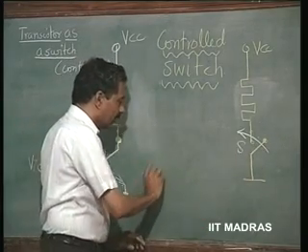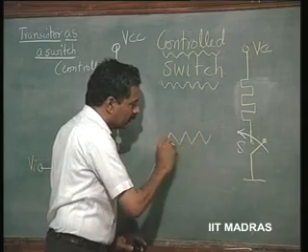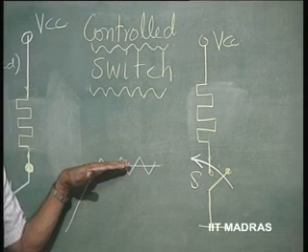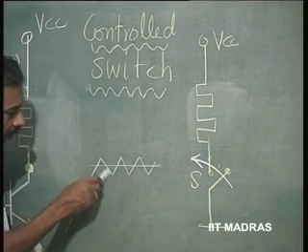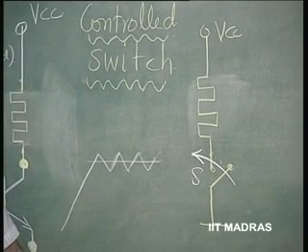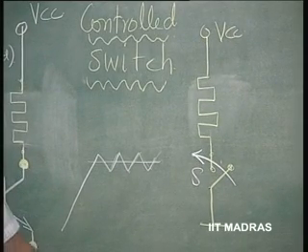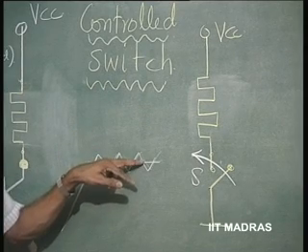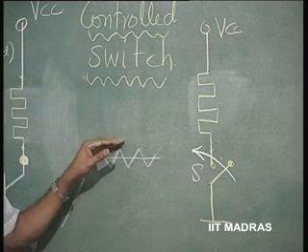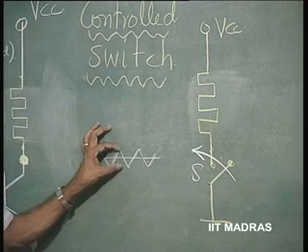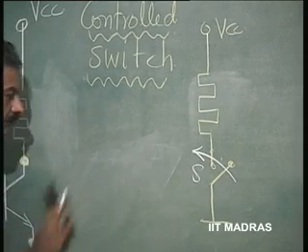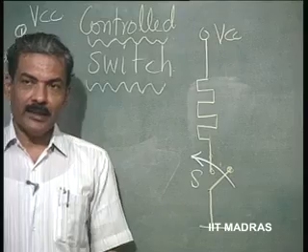This will normally remain at a constant temperature, around a constant temperature, so that it is off on, off on, off on. So, that controller is called an on off controller, a very simple controller. Therefore, it is never going to reach this set point temperature ever. It will always fluctuate around the set point by a certain set magnitude. This can be adjusted. Such controllers require a control switch. A transistor can be used as a switch.